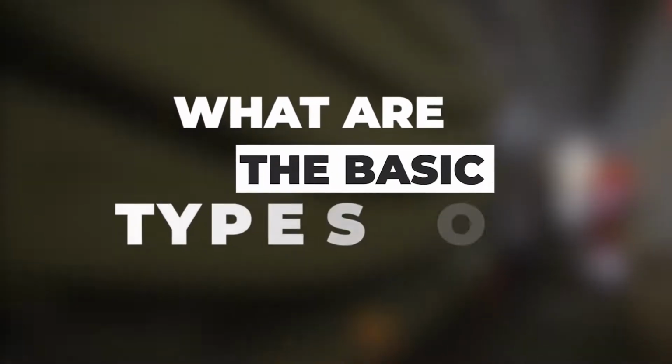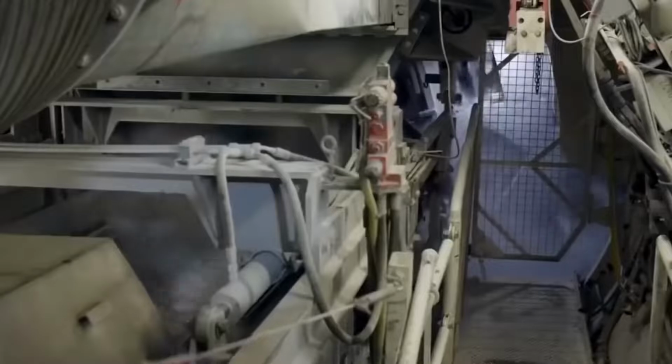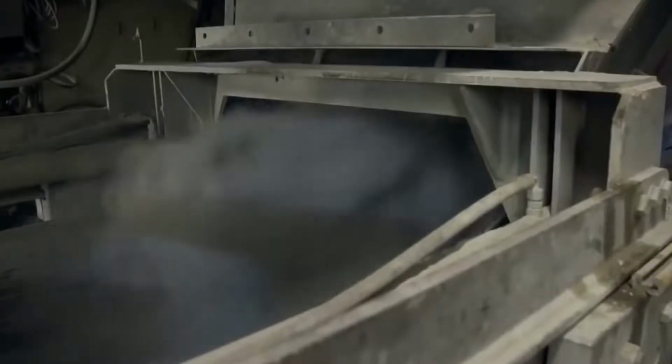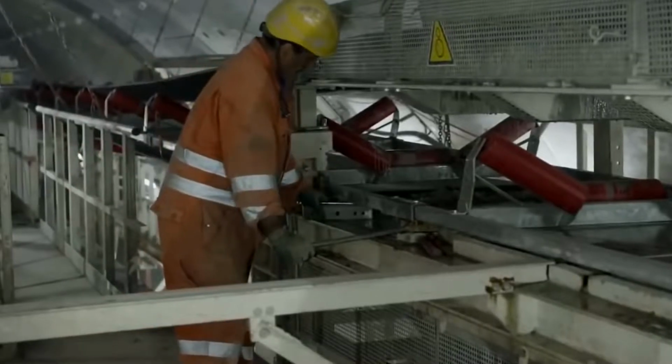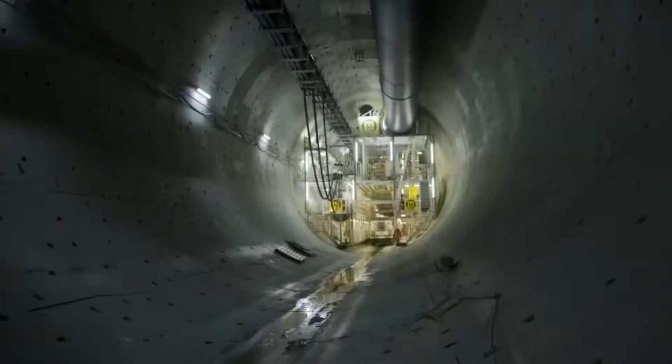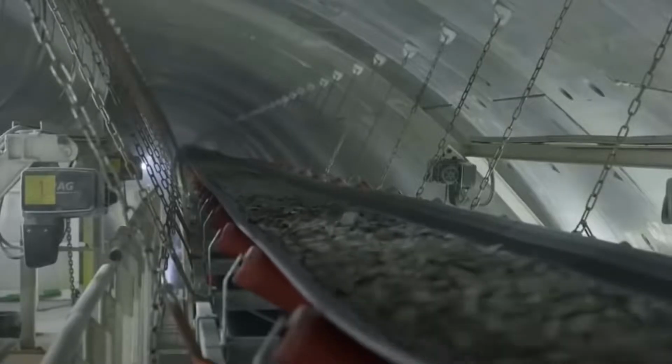What are the basic types of tunnels? Cut and cover tunnel, built in a shallow trench and afterward covered over. Bored tunnel, built in situ without removing the ground beforehand. They are normally of circular or horseshoe cross section. A few ideas of underground mining apply.